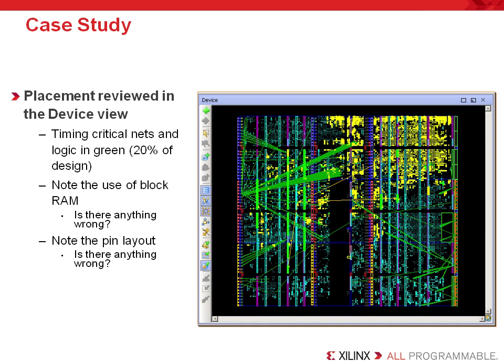Before floor planning USB Engine 1, examine the pinout and design connectivity. There are long routes to pins, so the logic will need to be placed near the pins.